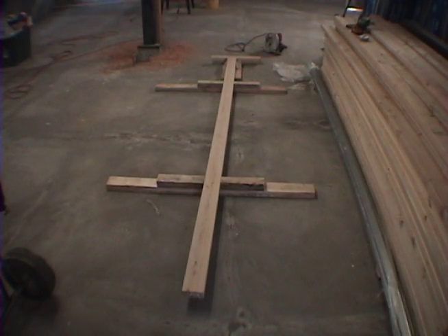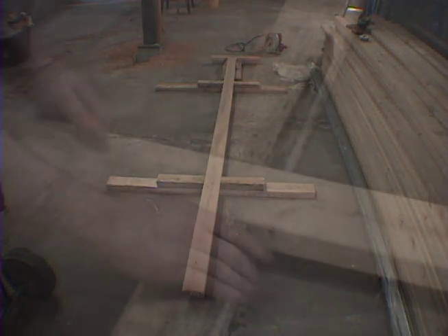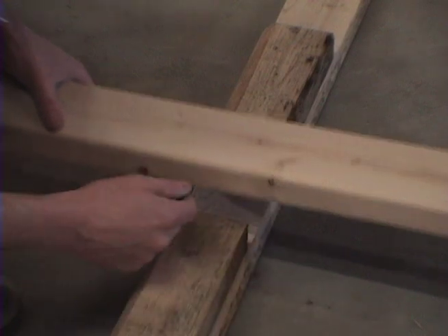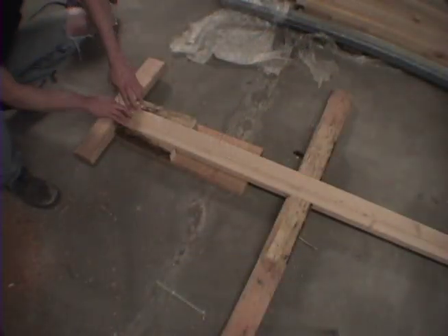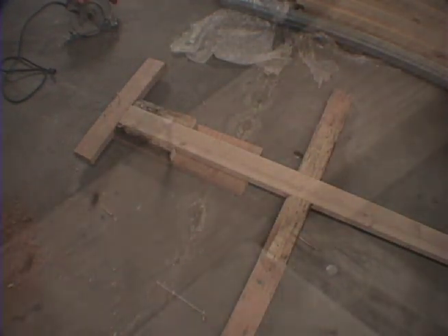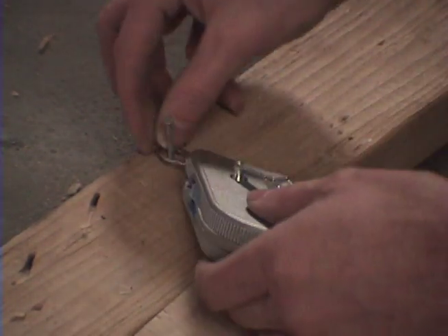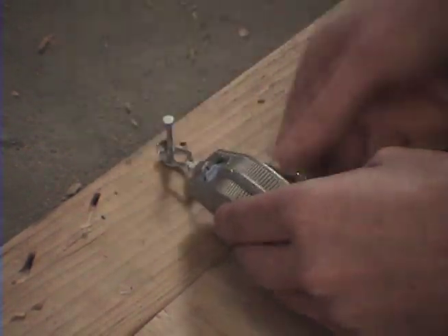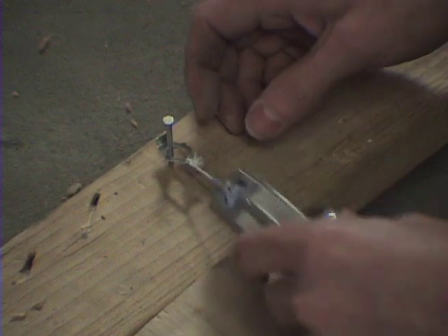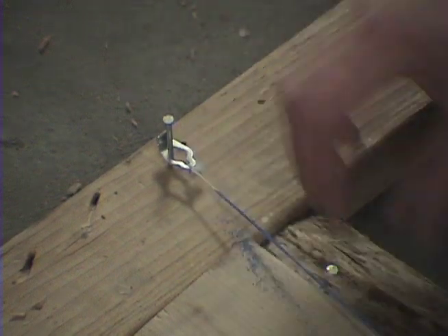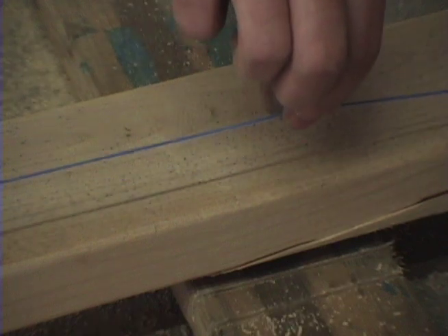If you have a table saw that would allow you to rip these 2x4s safely, then use that tool. I didn't have that, so I built a jig to raise them off the floor so I could cut them with a circular saw. We need to mark a line on which to cut. To do this, place a nail at one end on the corner of the jig, attach a chalk line reel to the nail, and pull it to the opposite corner. Hold taut and snap. This gives you a blue chalk line on which to cut.